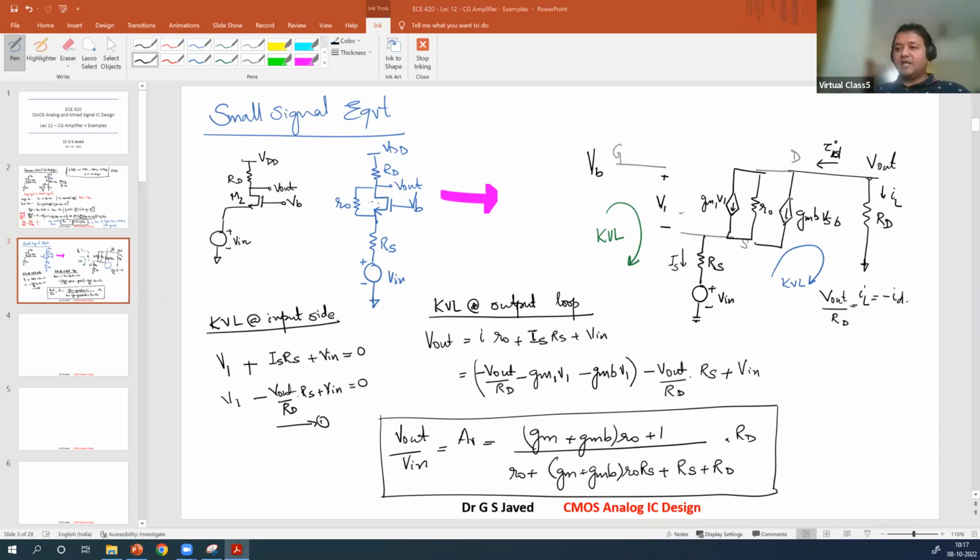So what do you infer from this circuit again? You infer that it is a non-inverting gain. Non-inverting gain, it has a gain larger than the CS stage. In this case, it is due to body effect. Here, body effect is a desirable feature.